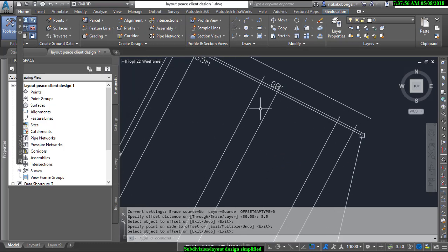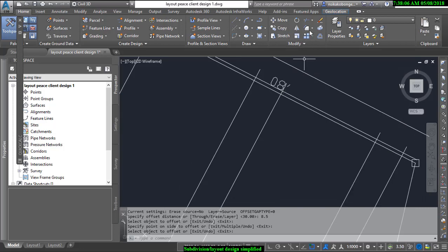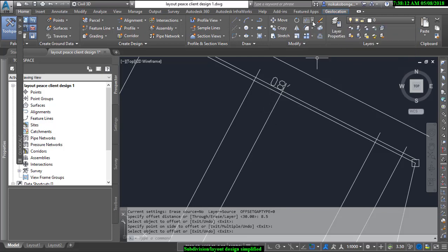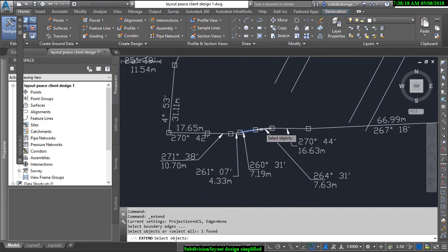And then while creating, before you work with your parcels, you must make sure there are no breakages or joints or lines that are not linked together while drawing your polygons. So I have to make sure no line is lagging or sagging or disjointed.